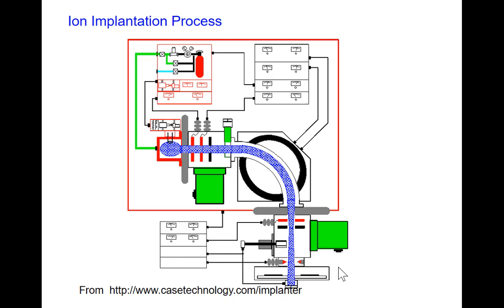And here are some explanations, and this is a picture showing it. You have some material here that will generate ions, and then you create an electric field here, which will accelerate those ions. You may use some magnetic field to change the direction, and then you can further accelerate it, and your wafer can be below it, and then it becomes high speed ion particles.